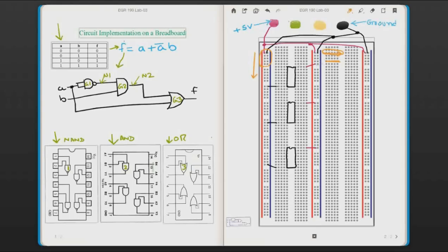Now with this, the other point I want you guys to see is all the ICs on page 1. If you look at the top right pin, it has VCC, VCC, and VCC, right? Similarly, the bottom left pin has ground, and has ground. So I took all of them, like all these are grounds, right?